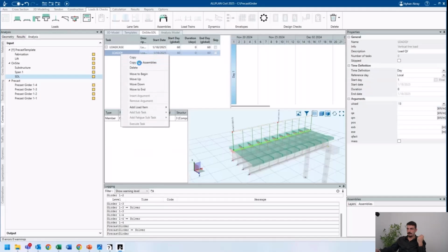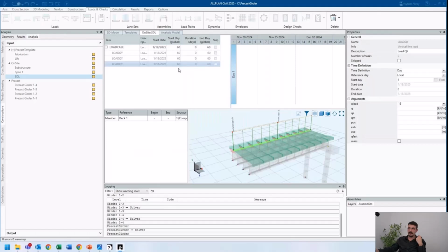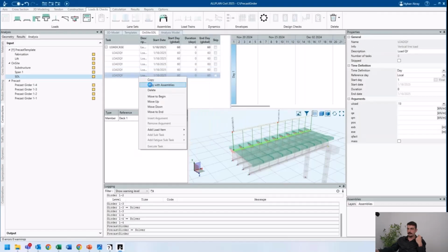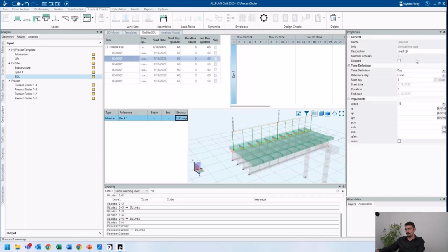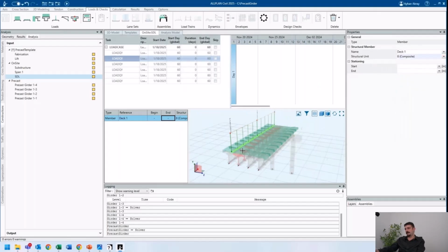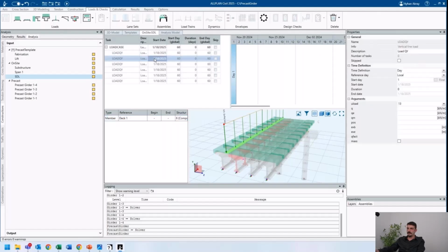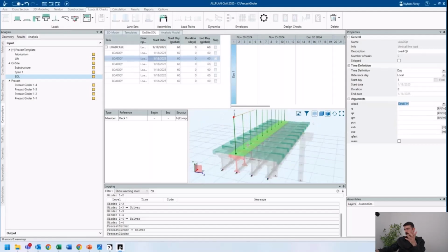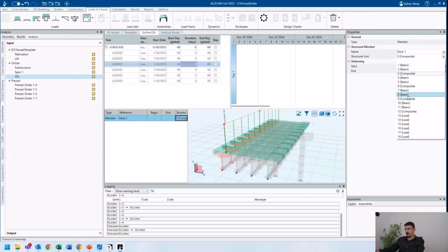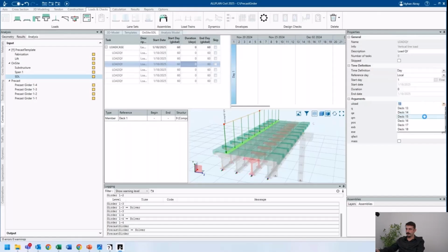And to do the other ones, I will just copy them again 6 times, because we have 6 loads in the system, like this. And for each different structure unit, we can say, I want to assign an asphalt load to the second beam, and I assign a second beam and simply change my asphalt, and it will be activated here. Don't worry, the precast girders are connected with Z-beam with grillage option, so that it will be distributed evenly. But in order to simulate this accurately, I am activating the loads close to that specific member.